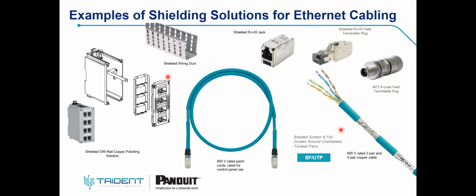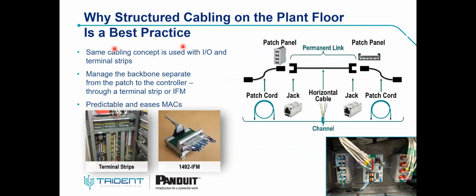It stands for high voltage and provides you cost saving by avoiding any need for separation of the cable, as we said in the previous slide. So you can be using this cable. You have different ranges of cable, 600 volt or 300 volt. Also the shielded wiring duct. This duct can provide additional protection from the noise producing source. Okay, now